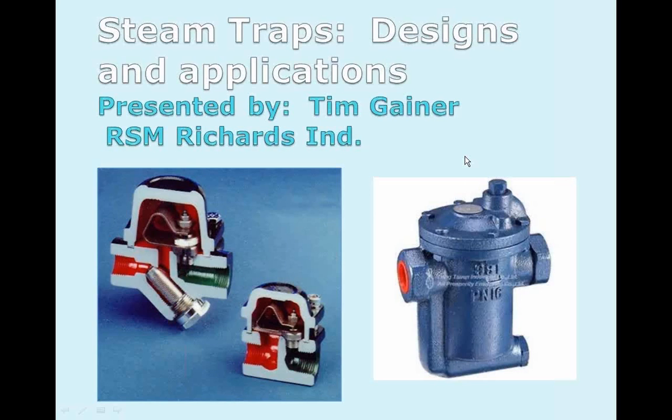of the trap. And this varies depending on the type of trap, whether it's cyclic, whether it's modulating, but there should be a decent temperature drop across there because you're only letting water out of the outlet side. Most traps will fail open, so if you find the temperature at the inlet and the temperature at the outlet is the same, you're probably blowing steam.